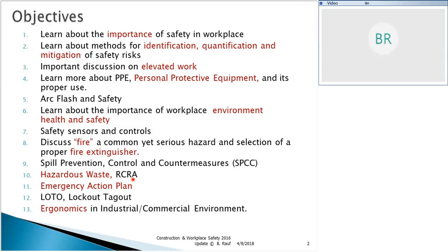You'll be surprised to see that a substance doesn't have to be ostensibly hazardous to be declared hazardous. If you've got an unknown substance stored in a drum, other than H2O, and you're not even sure that it's pure H2O, if you're not sure about anything stored in a drum, it's totally anonymous and unknown, you have to declare it hazardous waste, unless and until it is tested and proven otherwise. We'll cover more of that later on.